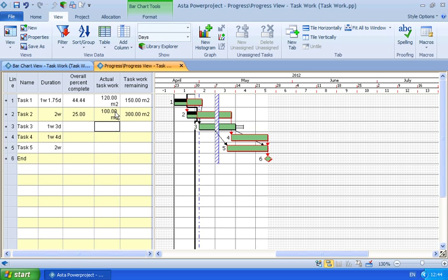Using Progress Expert in Powerproject, as you know, we can get earned value data and S-curves based on duration, so that's still possible. So again, without the need for resources, we're able to produce that earned value information. So all of this makes planning, progressing and producing earned value data from a schedule much easier in Powerproject compared to other systems where resource assignment is still a requirement.